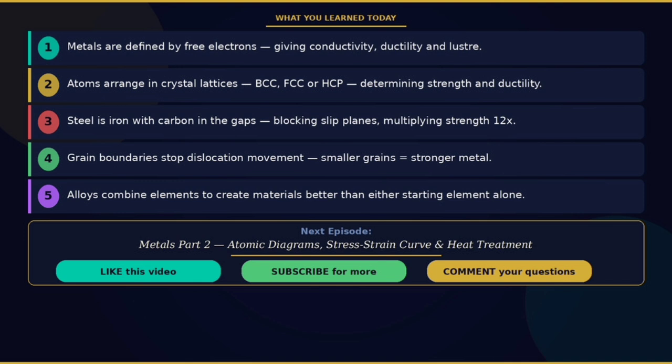Grain boundaries stop dislocation movement. Smaller grains mean more boundaries, which means a stronger metal. This is the Hall-Petch relationship. And alloys combine elements to create materials better than either starting element alone. Steel, stainless steel, duralumin, all engineered for specific applications.